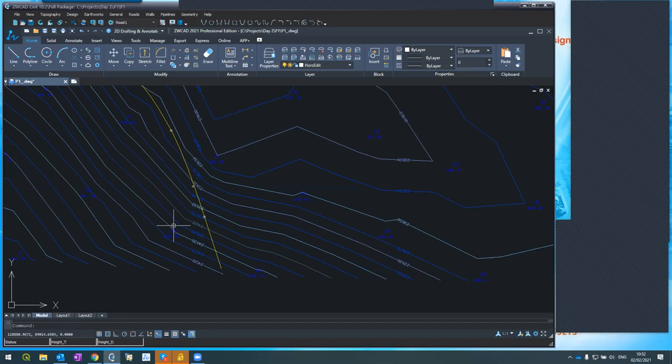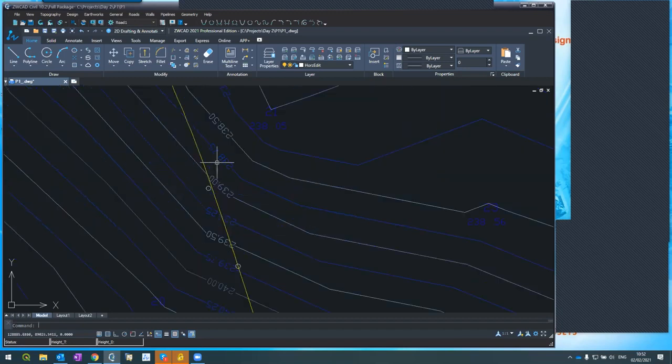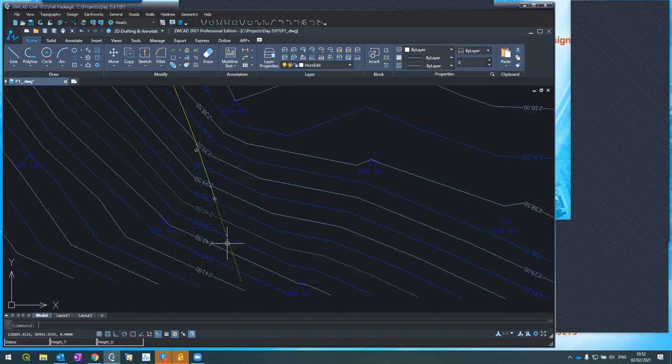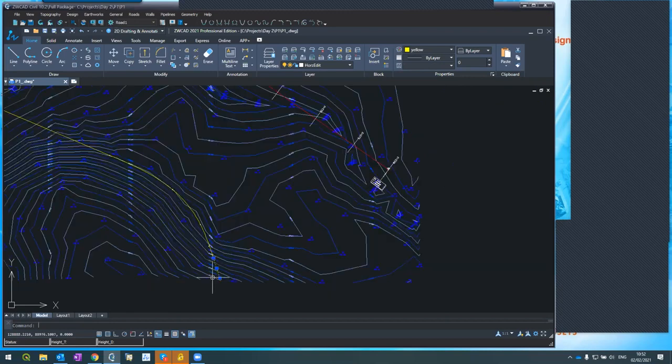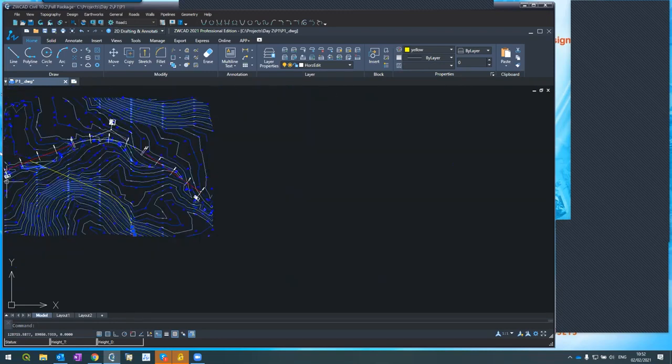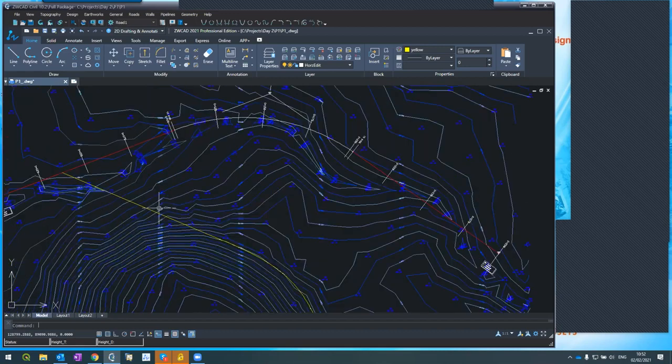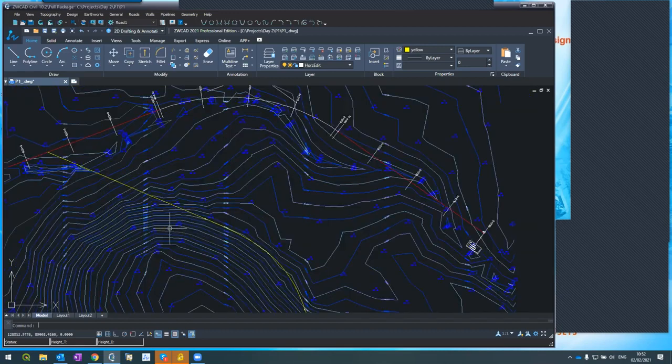Let's see, okay. So the system automatically connects this curve with this point using a tangent and a transition of 20 meters. This is the transition. And this is the tangent. I hope, this is quite deep into road design. I hope you got it. Most of you have got it. Excellent. Most of you have not got it. You will have to practice.